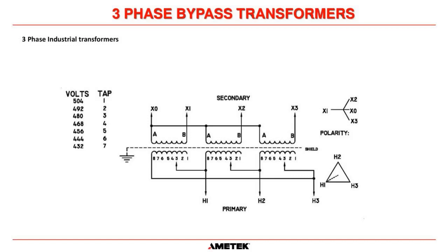If we have overloads on a system, the UPS, if it's overloaded, will transfer to the bypass. That's the function of the static switch. And what we don't want to see then is a low bypass voltage with no load. And when you put load on it, then the voltage drops further. And by the time we get out to the loads, we could be down in the low teens, maybe 111 volts. And we're approaching the minimum input voltage of the load then.